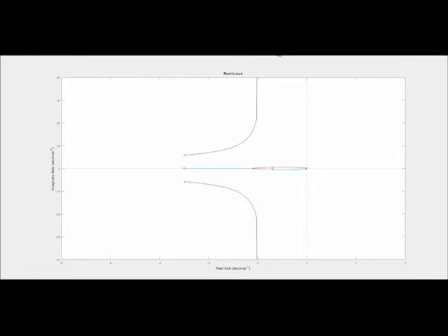Yes? So with the MATLAB command, is it assuming that you're changing the proportional gain? We'll talk about that in a little bit more generality, but it's assumed that you're changing a gain in your system. Yeah, you can generate a locus for that. Exactly.